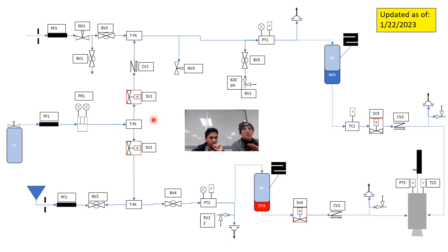So at that point, we have hopefully reached high confidence that our system is purged and there's only nitrogen in those lines. It's very important to note that as we're pressurizing and pushing out, we're closing, and all that's left is nitrogen in the system at higher pressure. So nothing should be coming in. At worst, if there's a leak, it's pushing out, just like a clean room. So now we can move on to filling the ethanol.